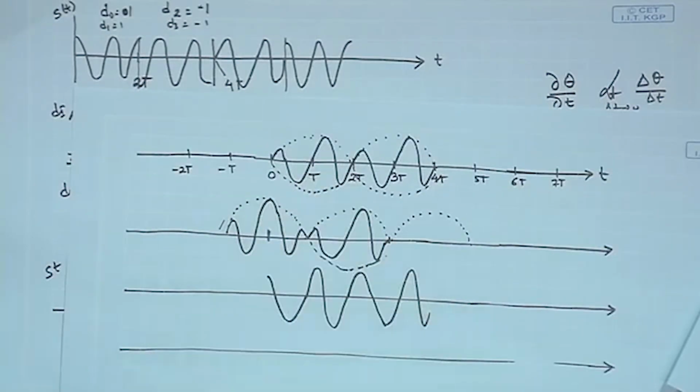So, instead of going for offset QPSK with rectangular pulse, you could go for offset QPSK with the half sinusoid pulse, which is also known as MSK. But offset QPSK with the rectangular pulse appears simpler, and it is straightforward to understand and probably decode compared to a half sinusoid representation or the MSK representation.